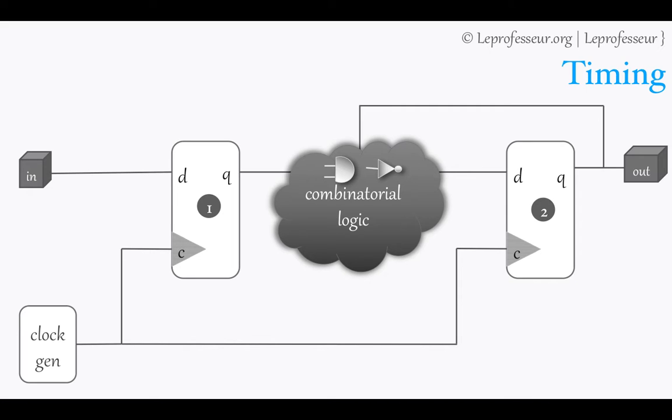So it is very important that the timing should work: how much delay it's going to take to do the computation and produce the result and create a valid state of the digital system. And by the time the next clock comes, all our computation should be ready, to utilize those computational results in the next clock cycle. Every flop is associated with a clock to Q delay.